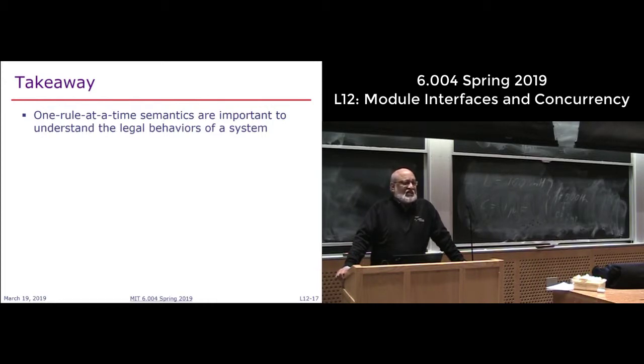And there are all kinds of annotations you can put in, so that the output will tell you what is the guard of a rule and guard of a method, and which rules can be executed concurrently or not. You just have to type that when you invoke the BSV compiler.